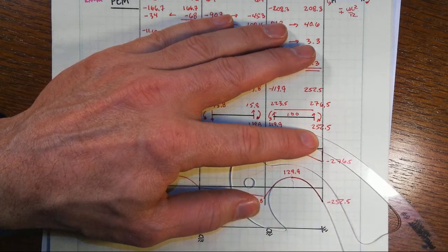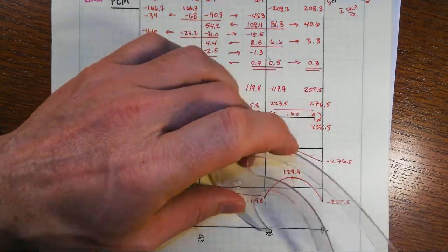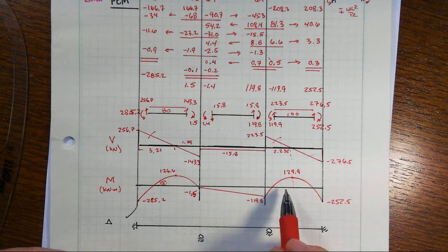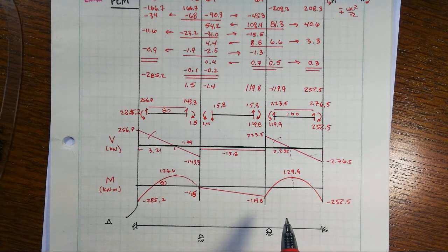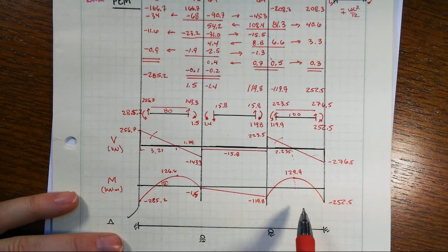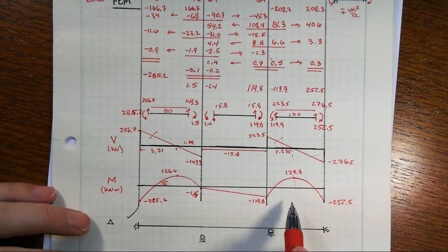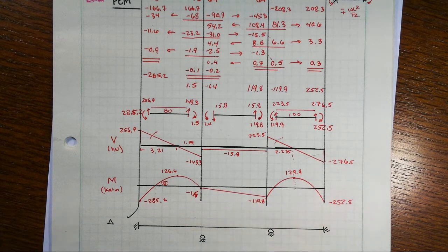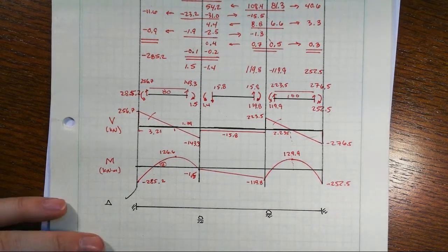If you're familiar with steel design, you know lateral torsional buckling and the CB coefficient. We have to go find things at quarter points and midpoints of the bracing pattern, to establish a lot of interesting aspects of the strength there. But notionally is what we're really interested in at this particular time.